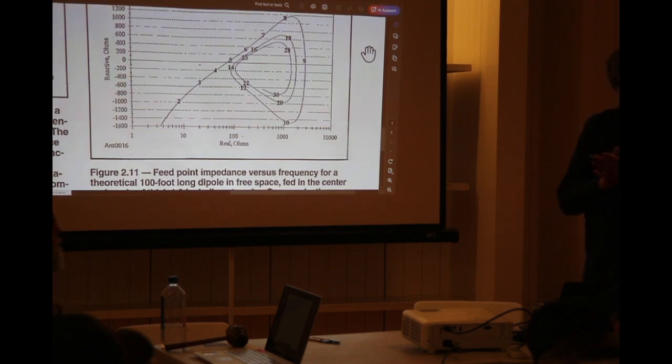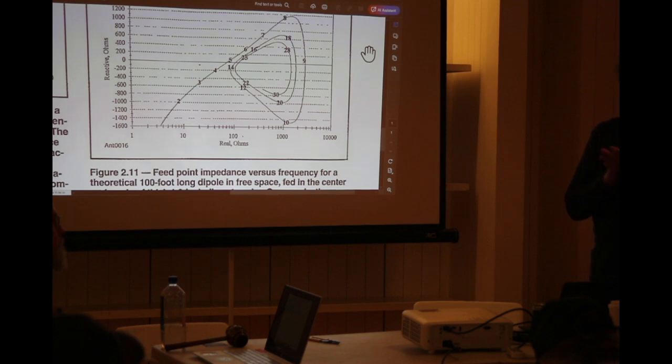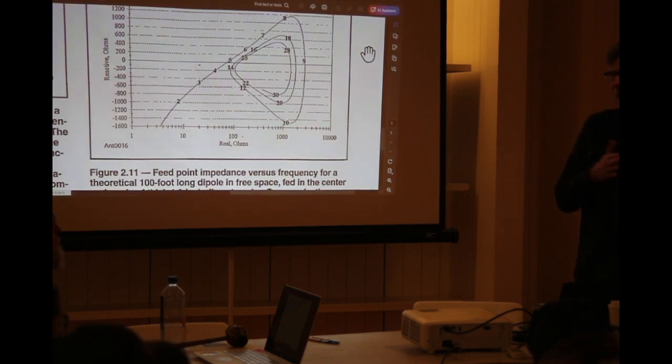So it's really good for that. You can measure either the magnitude going through the filter or the imaginary component going through the filter. You can do that both logarithmically or linearly. If you're designing a filter and say, boy, this filter really looks lousy, well, you're probably on a logarithmic scale, which compresses it. If you want to see what the filter is really doing, use a linear scale, and you can see how good your filter can be.